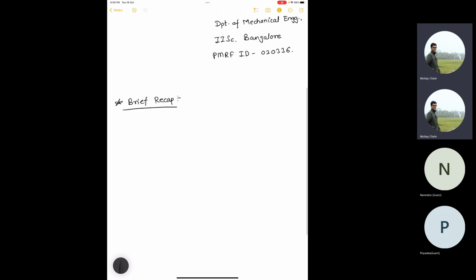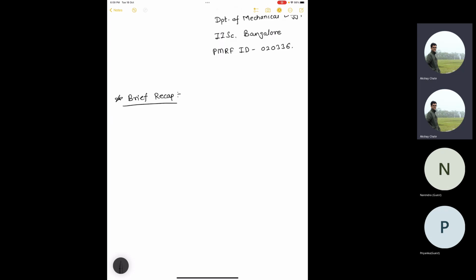What happens with the Brayton cycle? I'll be brief here, but you should know about this since it was briefly introduced to you. You have seen the maximum pressure and minimum pressure. If you plot the Brayton cycle on a TS plot, this will be useful for our Rankine cycle discussion also, because in the Rankine cycle there is phase change. In the Brayton cycle there is no phase change during the heat rejection process. Other than that, it's more or less the same thermodynamically speaking.